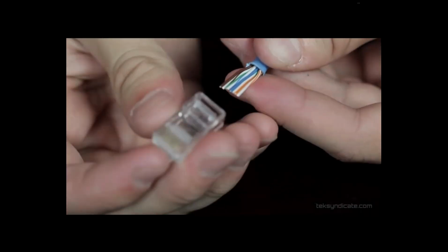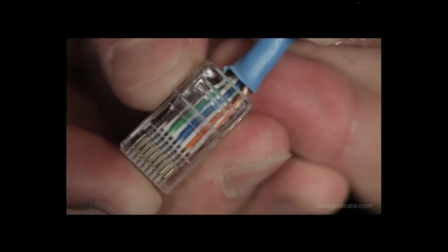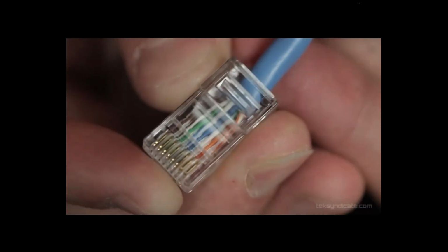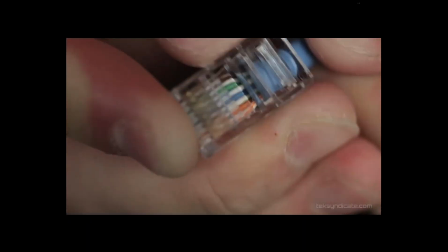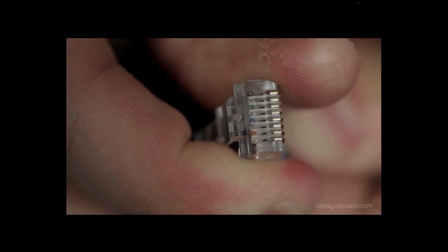Next, we're going to very carefully, and at this point, just double check your wires, make sure that they're again in the correct order. That's white orange, orange, white green, blue, green, white brown, brown. And you're going to be very careful. You want to set them inside, and I don't know if you can see it, the wires are actually being separated out inside the plug along little tracks, and they'll go all the way. Push it as far up as you can. Give it a little push. The sleeve will go up further. That's probably a good thing. You can check the end, and you'll see the copper conductors right along the end. That'll be nice and shiny.